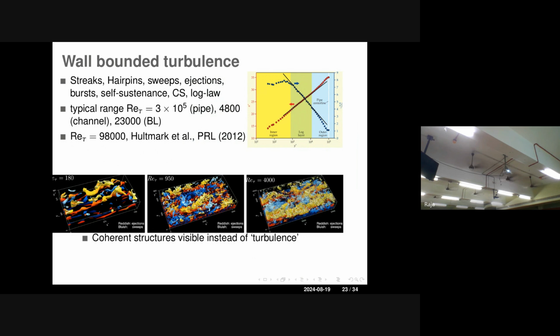When you increase the wall shear stress or wall Reynolds number, these coherent structures, the red high-speed and blue low-speed structures, break down into many tiny pieces, and it starts showing multi-scale nature. The predominant high-speed, low-speed streaks are always there, but they always have multi-scale fans coming out of them. What are these? These are streamwise velocity components superimposed on them.